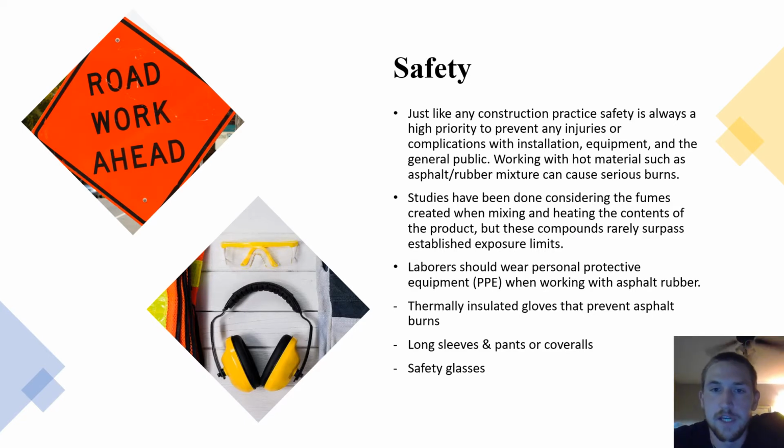An important one is safety. Just like any construction practice, safety is always a high priority to prevent any injuries or complications with installation, equipment, and the general public. Working with hot materials such as asphalt rubber mixtures can cause serious burns. That's really the biggest hazard, but studies have been done considering the fumes created when mixing and heating the contents of the product, and they found that these compounds rarely surpass exposure limits.